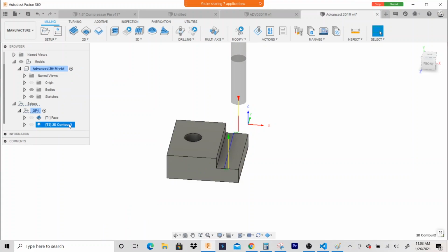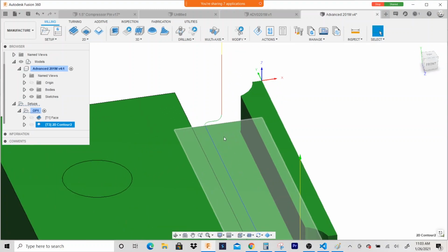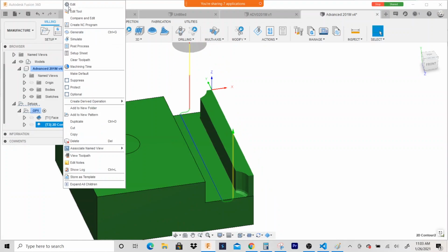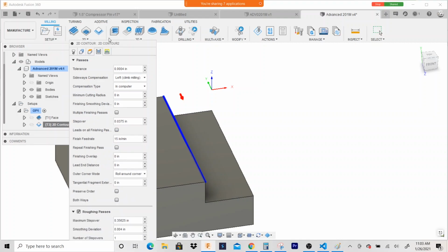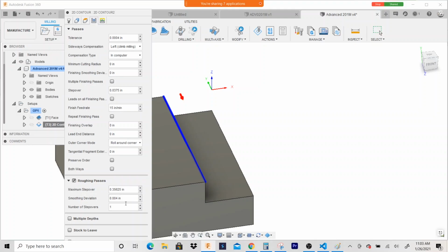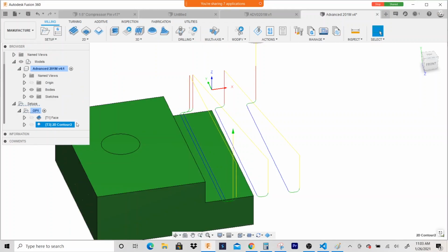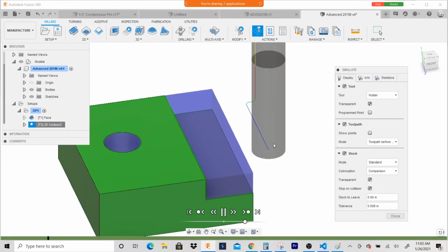And this is the toolpath it gives me. Now this toolpath, there's issues with that, and that's because I'm using a 3/8 end mill, and this flat is wider than 3/8, right? So it doesn't cut everything. So what I'm gonna have to do is on my passes, I'm gonna have to add rough passes, and we'll say 3 passes. That might be a little bit much, because this first pass at 3 is going to be cutting air, so it's not even touching anything.